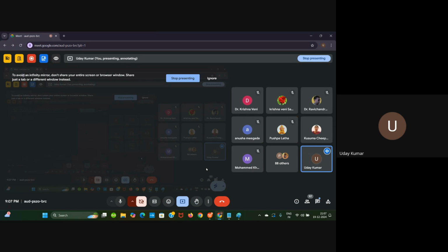In the CTS stage and then the route stage, suddenly there were some interconnect bottleneck parts where they were split out as a fan out, and that particular path that has split out as a fan out is failing as hold. Like the same cell through which my setup is failing has also failed another path for hold.